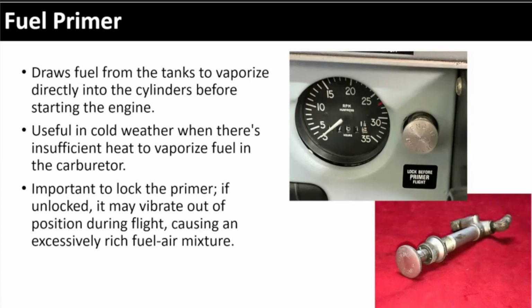Okay. The primer he's talking about here. Again, the primer, we don't see them in cars anymore. Way back in the day we did. But the primer is just a way to prime fuel and vaporize it to get into the injection system or into the carburetors to make sure that it's ready to go when you take that magneto and turn on the starter switch. Okay. You want to make sure that